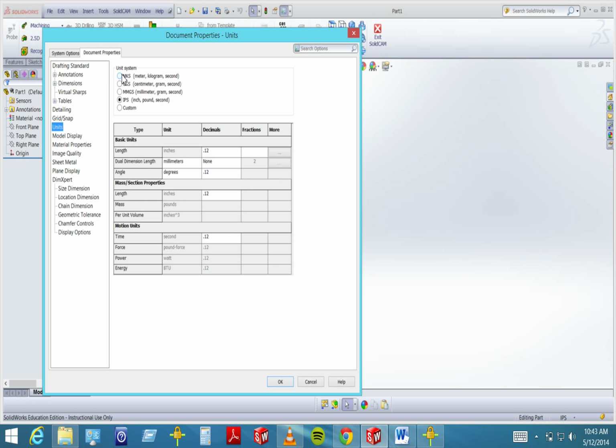You are not going to find a 5mm thick 6061 T6 aluminum plate unless you want to pay 10 times as much to have it shipped from China. You're not going to find it. It's built here in America. They're a 1/2 inch. So when you're designing your part and you want it to be out of a piece of material that you don't want to have to machine too much off of, you need to think, okay, I can get 1/2 inch plate, so I'll just figure out what that is in metric units, and that's what I'll type into my model. See what I mean?